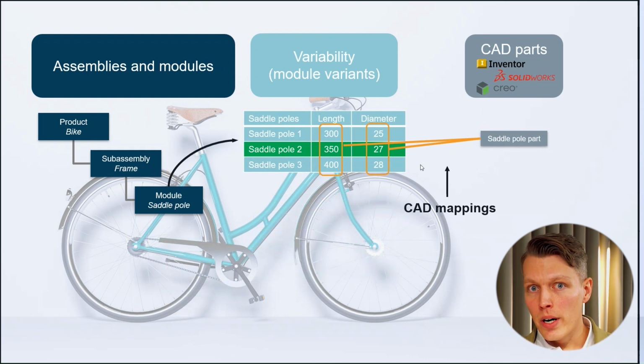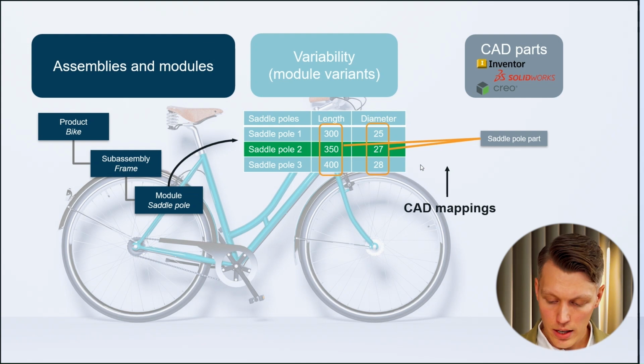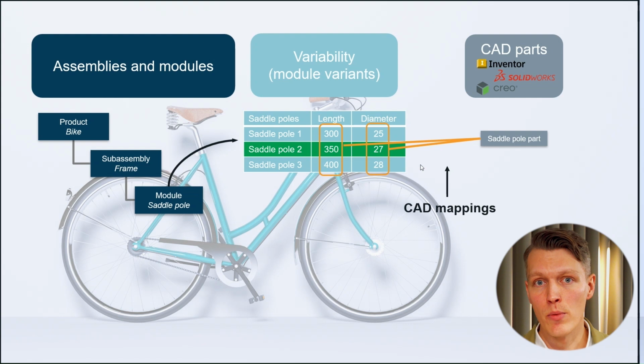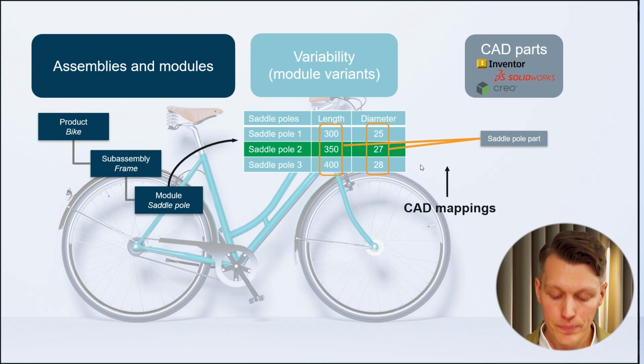And here is really where we can utilize the power of Tacton's configurator together with CAD automation. So if you have anything in your product that needs to be cut to a certain length, for example, raw material like a beam or a pipe, imagine trying to model that with discrete variants, all of the different combinations. It's nearly impossible. We can create a customized length for a beam or a pipe, cut it to the exact length during production.